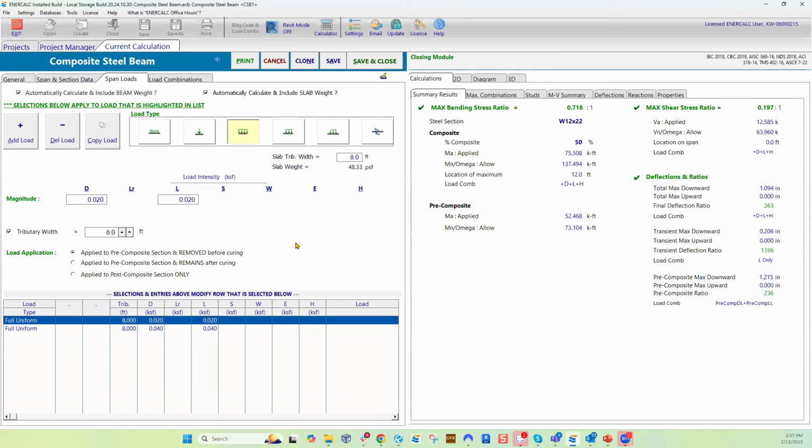On day one, they just put a steel beam, they put a metal deck, and they start doing construction, jumping on it, bring their equipment and do all that stuff. So you want to make sure that that load is accounted for in a way that the steel beam can handle that load by itself and within a deflection allowance that everybody's okay with. You can't have a 4-inch deflection on your beam because that's a problem. So that's why sequencing the load is important.